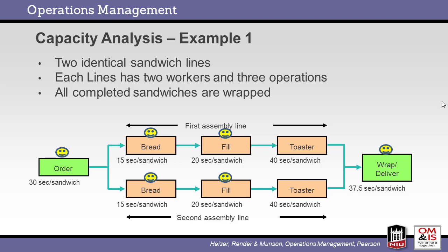Here we see a process flow diagram with three processes in series with two queues to isolate them. We see that process B is the bottleneck since it takes the longest time per unit produced. Process B cannot keep up with the product created by process A, while process C will regularly have to wait for process B to produce more material. The throughput time in this example would be 2 minutes, plus 4 minutes, plus 3 minutes, for a total of 9 minutes.